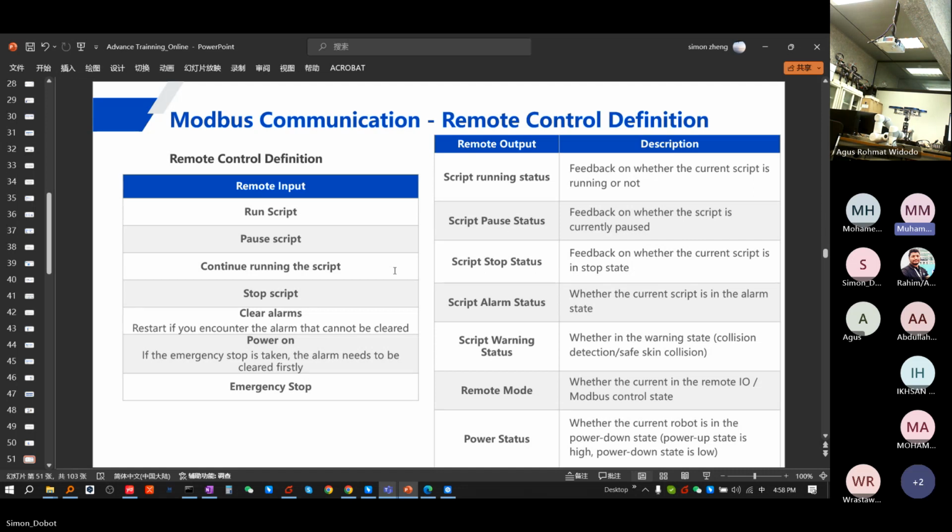So can we have a client application connecting to multiple robots using Modbus TCP? So you mean you have your PLC and connect to our different robots? Yeah, getting data and controlling two different robot arms. Yes, our robot is a slave. It can be done.